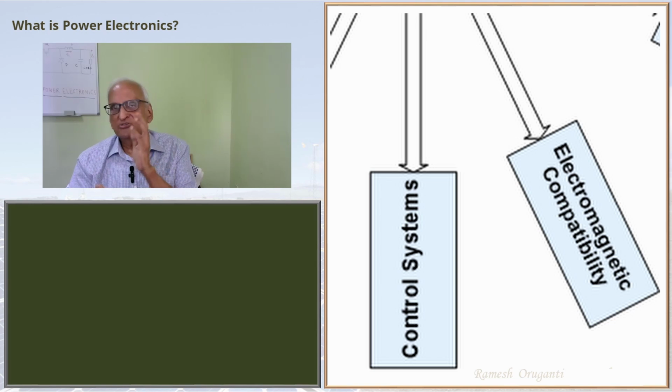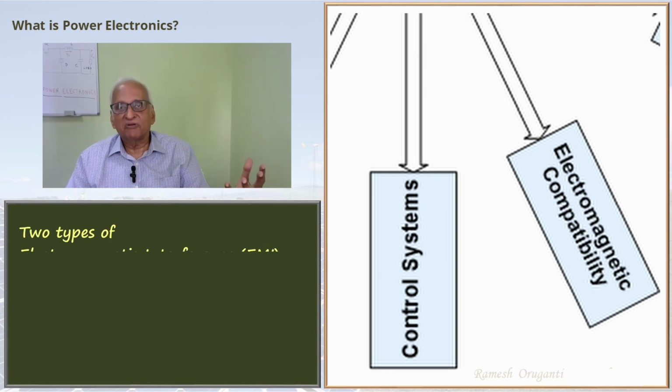The switch turns on, the switch turns off, so the current flows, the current is blocked. This produces a lot of electromagnetic radiation, very often referred to as electromagnetic noise. And this electromagnetic radiation can interfere with equipment, electronic equipment, communication equipment, for example, outside the power electronic equipment.